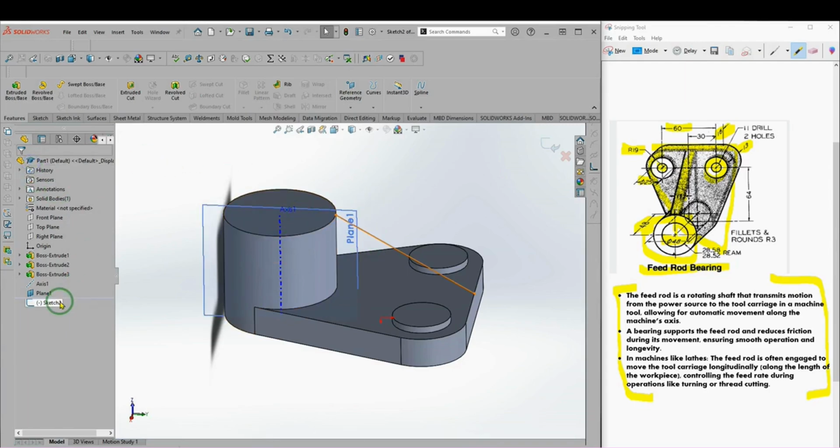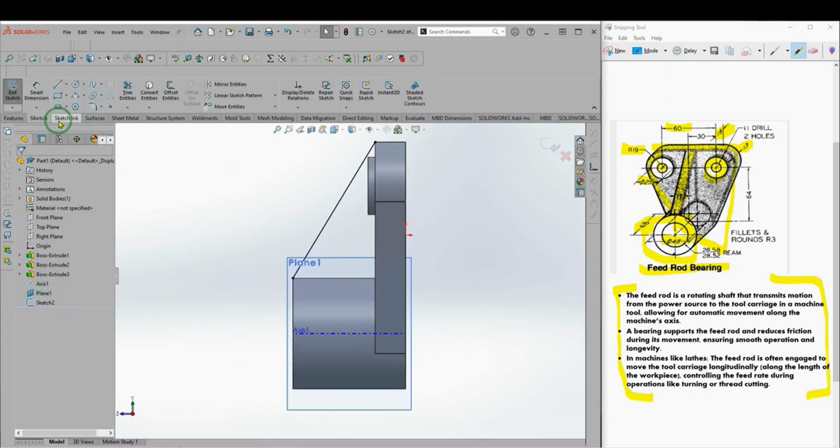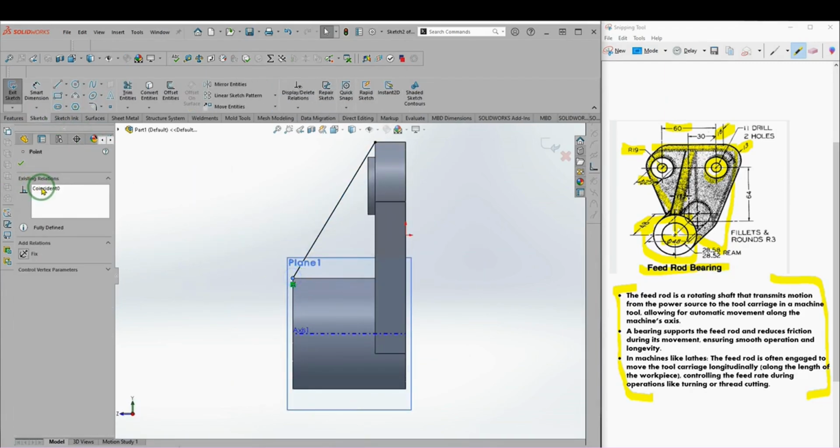You can come out of this sketch and again select Edit Sketch. There is a coincidence, delete all here. If the rib is given like this, we can easily make the rib, but at this point of curvature, it is very difficult to create the rib using the rib tool.